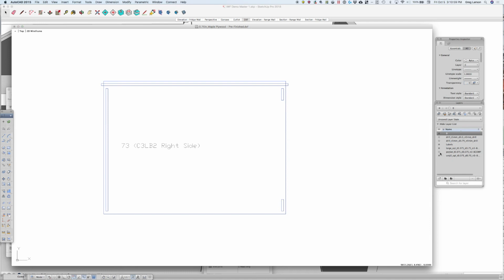If we look, our large outside perimeter is here, and we're saying large outside perimeter. The tool is a 3/8 inch bit. The depth is 3/4 of an inch, and we're using the 3-8 comp bit to do the cutting. And then we have the pockets. So the pockets are simply rectangles overlaid with the boundary of the pocket that we want to cut.